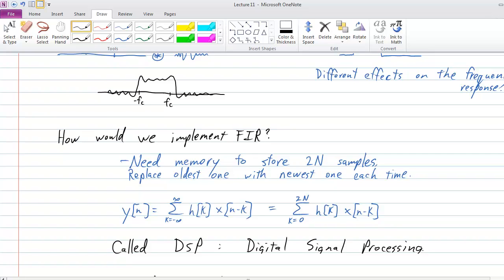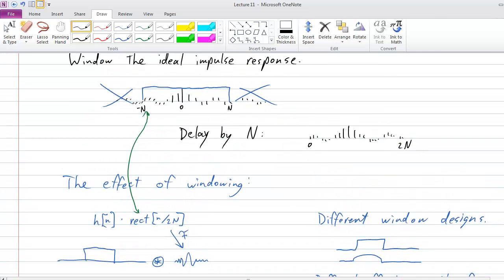But this K, is this in the time or the frequency? It's in time. Okay, so we're taking the impulse response, which is not this, it's the other one. We're taking the windowed thing, H of n, right? Yes. So to actually implement it, you convolve H of n with what's coming in, the input. Yes, exactly.